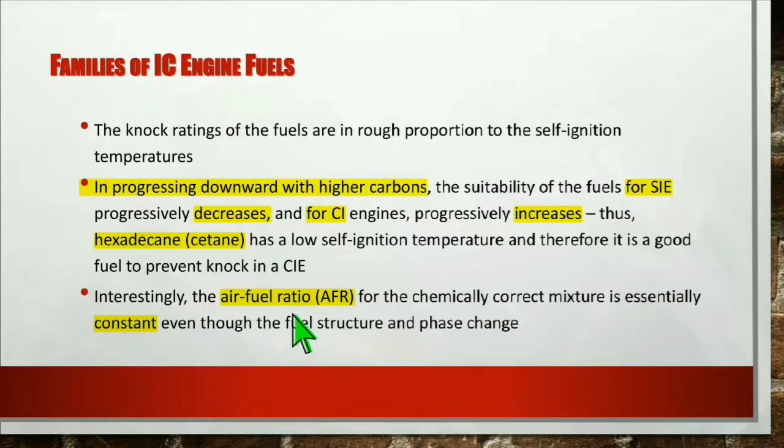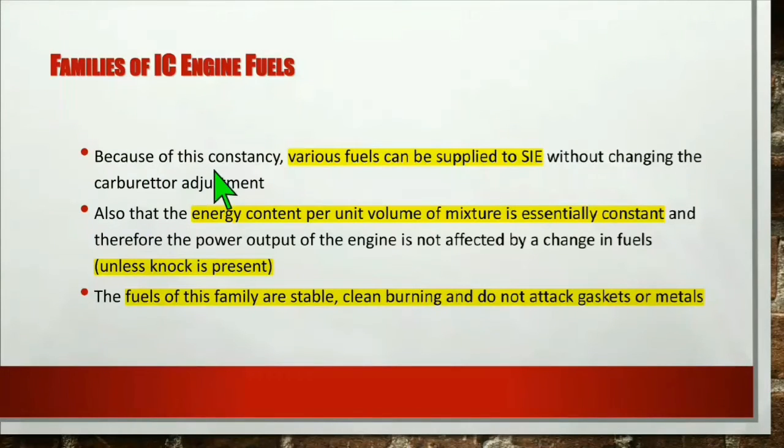Interestingly, the air-fuel ratio, AFR, for the chemically correct mixture is essentially constant even though the fuel structure and phase change. Because of this constancy, various fuels can be supplied to an SI engine without changing the carburetor adjustment. Also the energy content per unit volume of mixture is essentially constant and therefore the power output of the engine is not affected by a change in fuels unless knock is present. The fuels of this family are stable, clean burning and do not attack gaskets or metals.